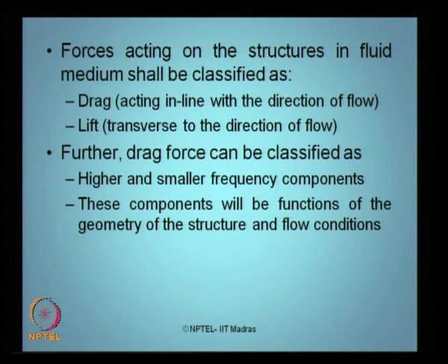So drag force can further be classified as having components of higher and smaller frequencies, because drag forces will have components of different frequency bands. Why are we interested in dynamic analysis in frequencies? Because we are talking about the frequency content of the force generated by the excitation phenomena, and the frequency due to the natural or dynamic characteristic of the system itself. So drag has components with both smaller and higher frequencies.